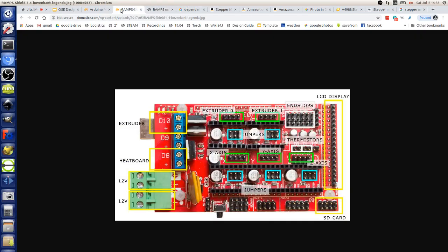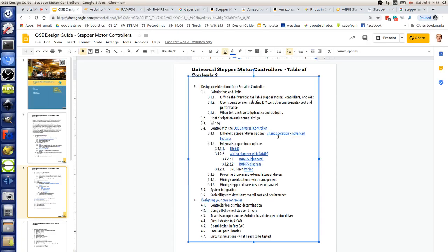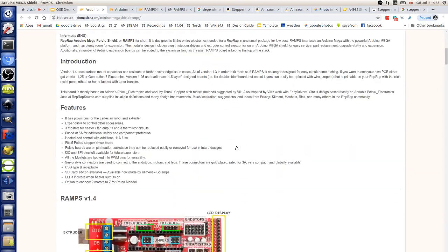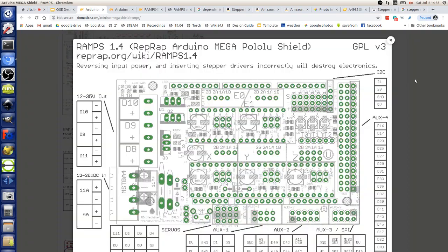Okay, so going back to the design document. That's RAMPS in general, but more specifically, if you ever need to hack it, you want to look at the deeper diagram right here, which shows you more information about what's underneath. For example, under each of these double row stepper motors, if you look at the fine print, there's the EN under the first pin. And then farther along, there's STEP, you can read the ST there, and then DIR for direction.